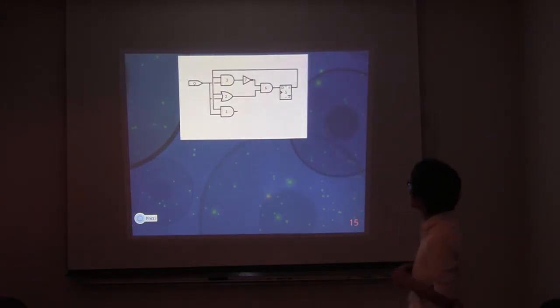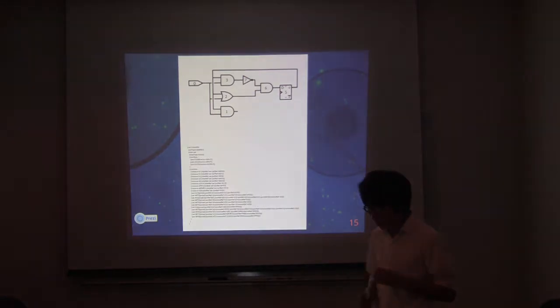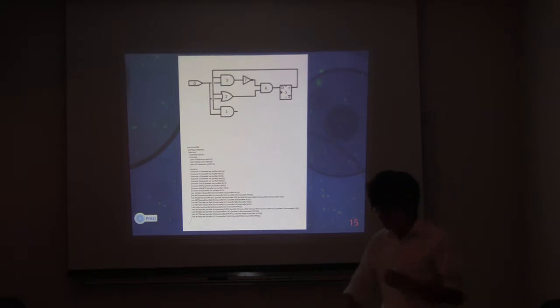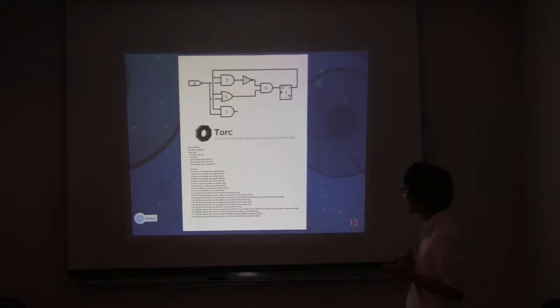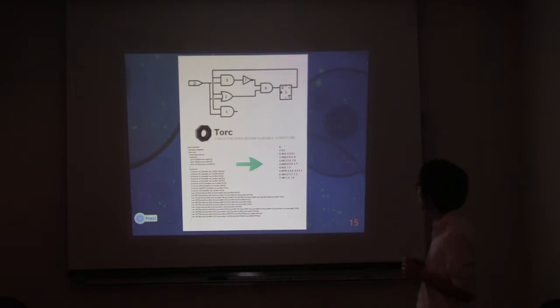First, given the circuit a user is designing, as far as Zero goes, Zero will generate a netlist in the format of EDIF. Once the EDIF netlist has been generated, Torc is used to read in the netlist in order to extract the digital components of the netlist. From there, a graphical representation can then be built.